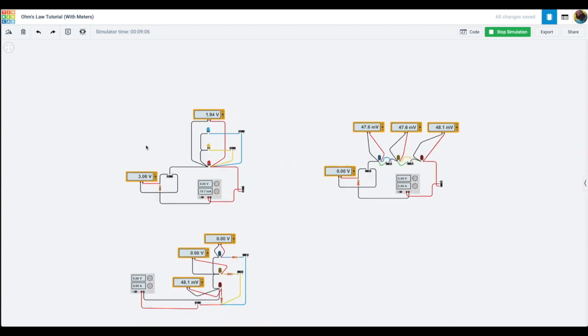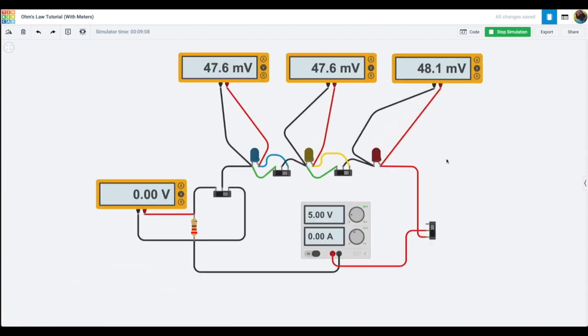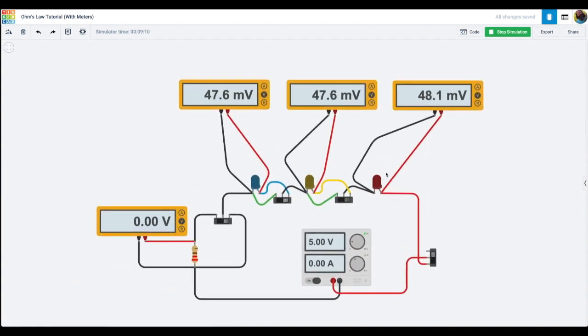Now, as an example from a previous discussion we had, these LEDs are in series, which means that if one goes out, they all go out. But I've got them bypassed right now so that I can have just 1 on, or 2 on, or 3 on, by having these wired the way they're wired. And I've got 5 volts just like before. If I turn this on, you'll see that each one of these is dropping 1.67 volts, and nothing's going across this resistor right now.